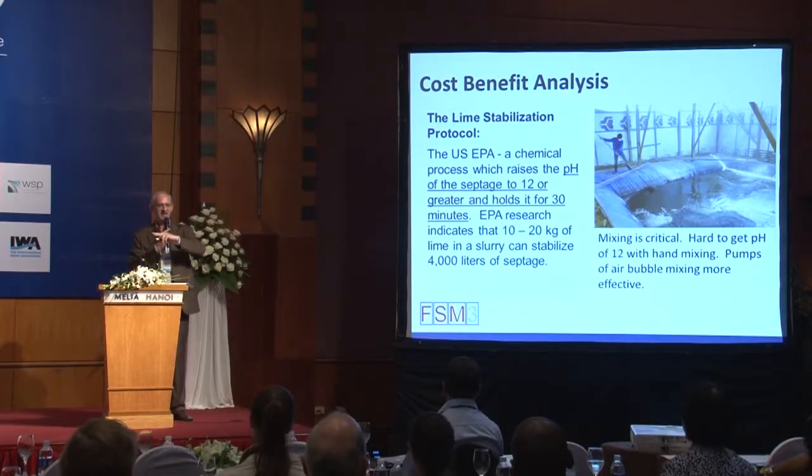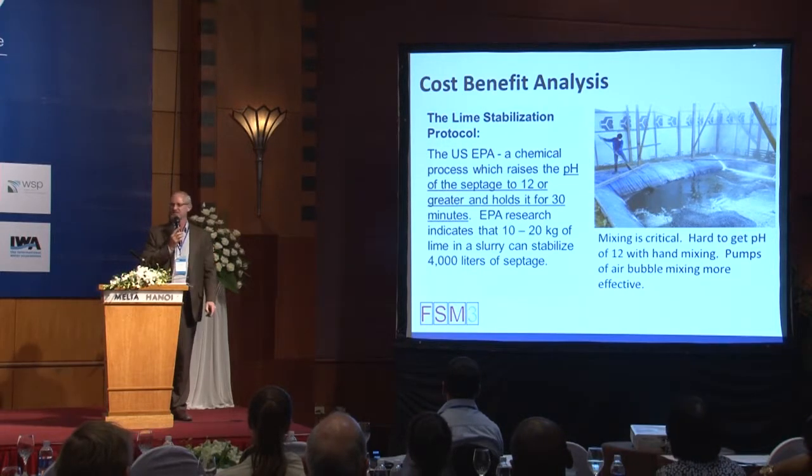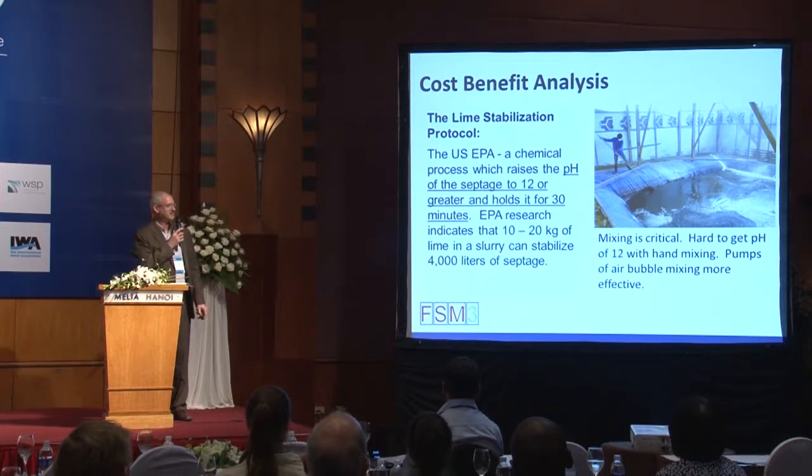They'll let it settle for a day, and then they'll pump off the supernatant, and then manually cart out the solids to a drying bed where it bakes in the sun. That really is not the best system, but that's what they're doing until they can come up with something better. At least it's treating the waste, and it's being done at pretty low cost right now.